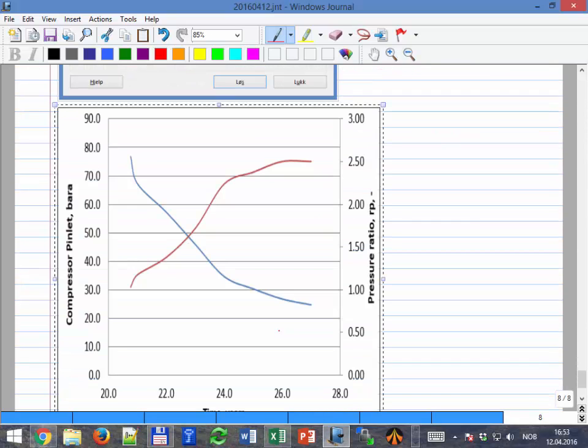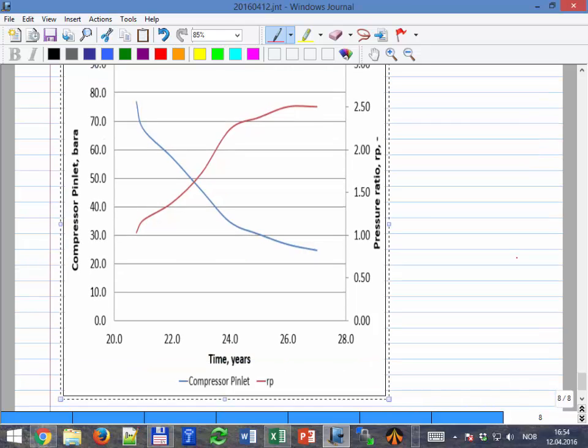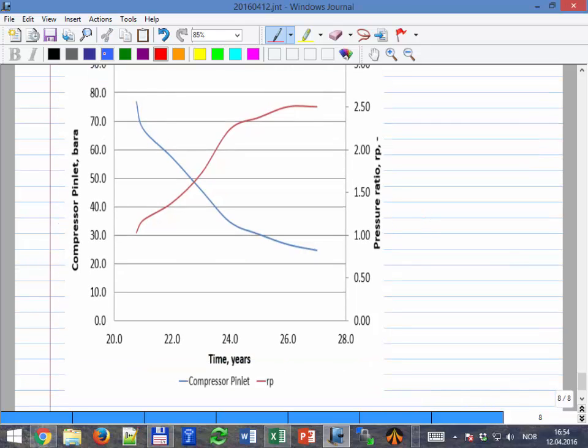Okay, so suction pressure goes down with time. That's suction pressure, P suction. And pressure ratio goes up with time. Okay, but not much. Still is within the limits that we saw initially when we ran without the solver, where we saw a very high number, 20. Usually the compressor should be all the time between 1.0-something all the way to maybe 3. 3 is already too high, but that's typically the compression ratio of a compressor.